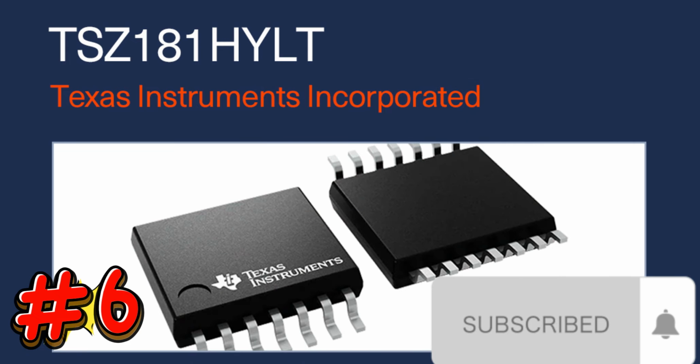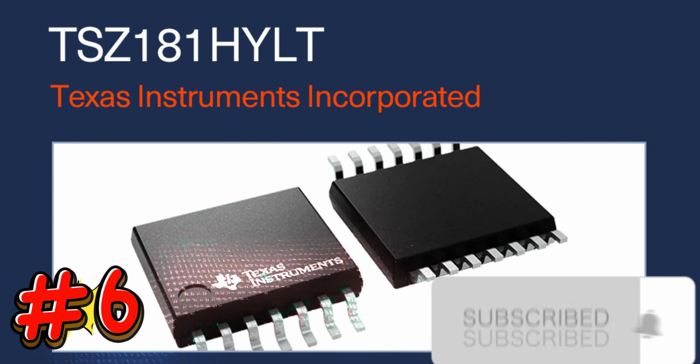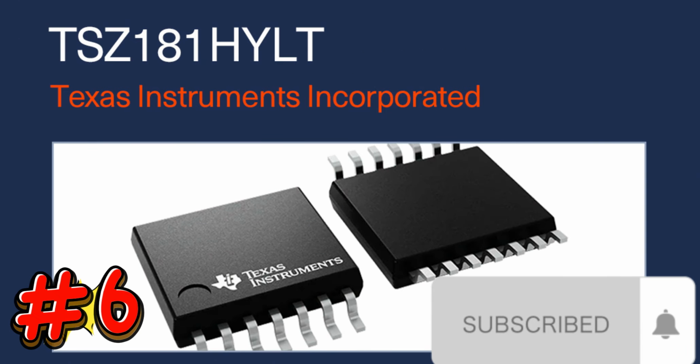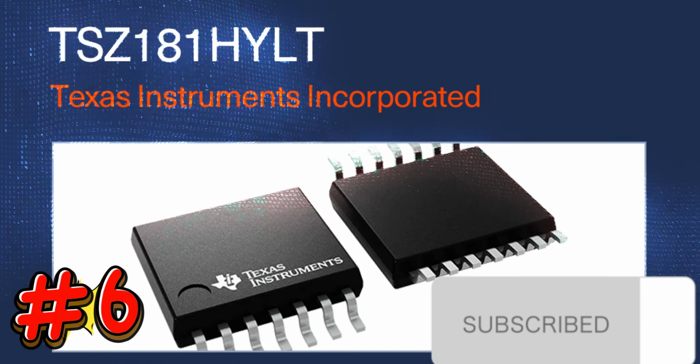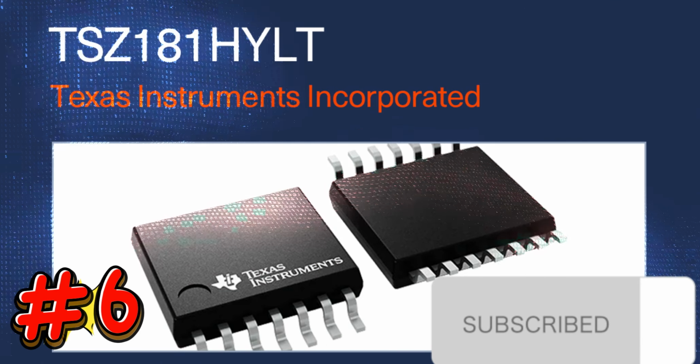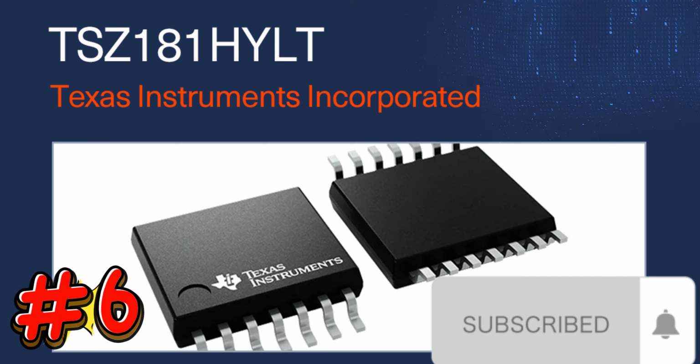As a result, along with the low supply current drain being independent of the supply voltage, the applications for the LM2902B-Q1 include transducers, amplifiers, DC amplification blocks, and conventional operational amplifier circuits, which can be easily implemented with a single supply voltage system.